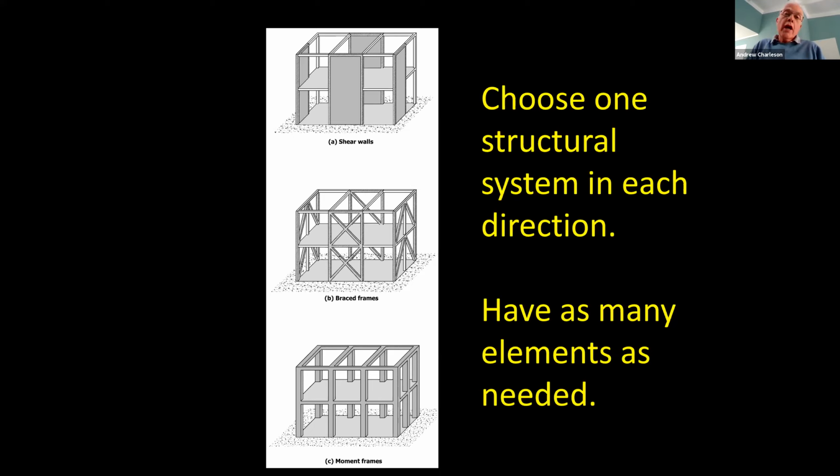If you want to, you could have moment frames in one direction and braced frames in the other. Or you could have moment frames in both directions. But you have to make the choice and show the structure in your drawings.